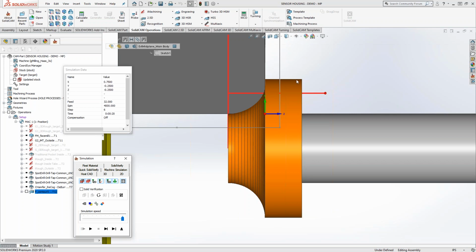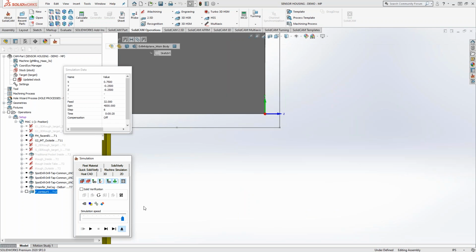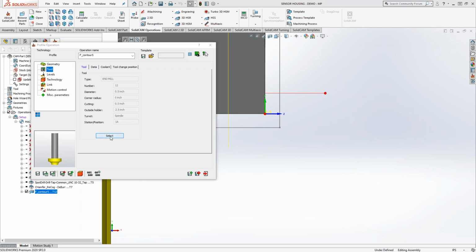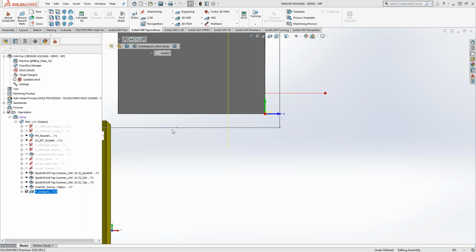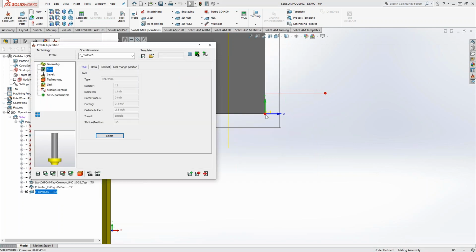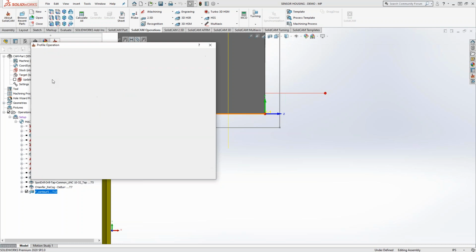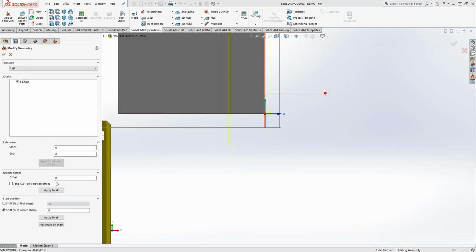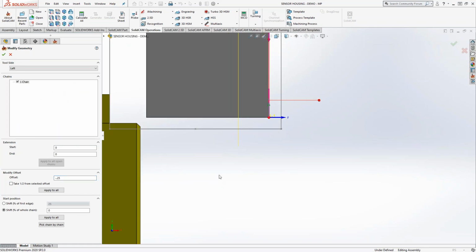So you want to basically just have an idea of the shape of your tool and how you want to shift it. So if we go back, let's say we had a tool like I defined it without the actual nice shape of being able to say that this is a 1/2 inch on the bottom. Let's say I know I have to shift it by a certain amount. I can still grab the same chain from the geometry, but what I want to do is use the geometry section to actually add a negative offset. So in my case, I'm actually going to do a -250.